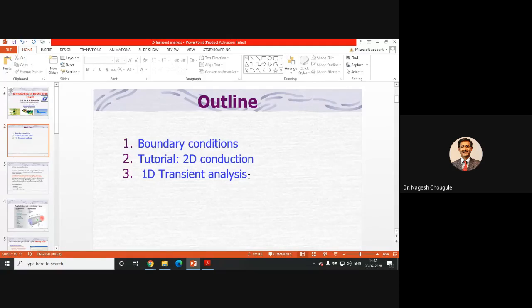In a given problem, suppose there are hundreds of variable factors. Out of that, the more relevant or more sensitive parameters we can filter through the sensitivity analysis. In sensitivity analysis, we have two types, local sensitivity analysis and global sensitivity analysis. In global sensitivity analysis, suppose 3-4 variable factors are involved in the problem, so interdependency is also calculated, or the effect is measured using the global sensitivity analysis. Whereas in local sensitivity analysis, the effect of only one parameter is analyzed on the whole system.